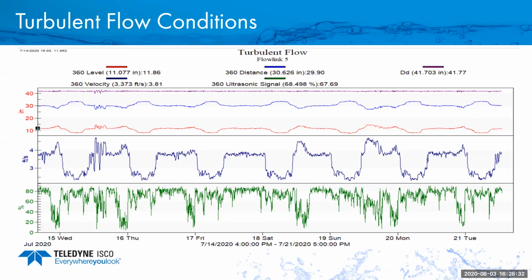However, it would be advisable to have someone go out and inspect this flow, especially under the higher flow levels, where we see that that is when it's having the greatest problems or the diminished signal. And specifically, it's the transition from low to high flow levels that we're seeing this, or excuse me, it's when it's at the tail end of the high level and getting ready to drop that we're seeing this diminished signal strength. So it could be a hydraulic condition that just exists in this pipe, and if we're aware of it, good.